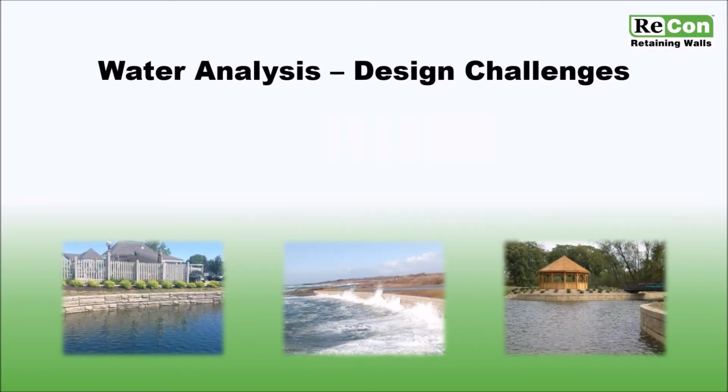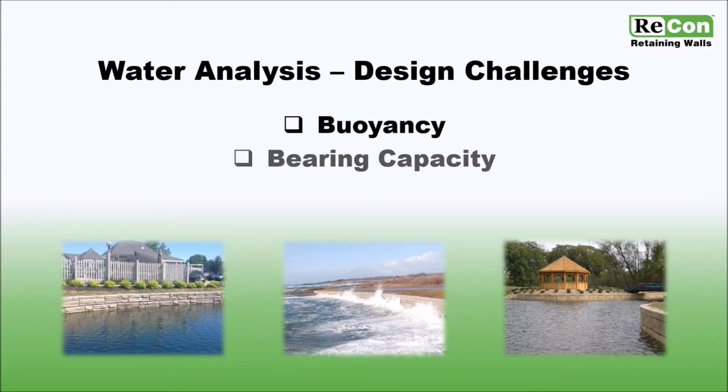Water adds several design challenges to retaining walls that must be addressed. These key challenges include buoyancy, bearing capacity, and differential pressure, sometimes referred to as rapid drawdown. When these conditions are present, they should be considered regardless of whether you're doing a gravity wall or MSE wall analysis.